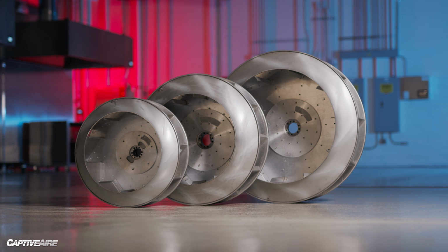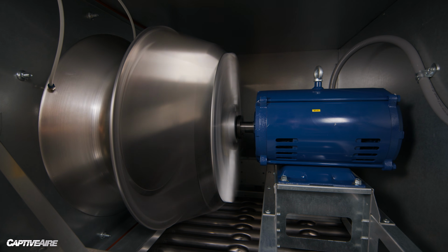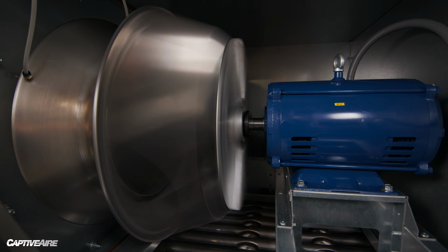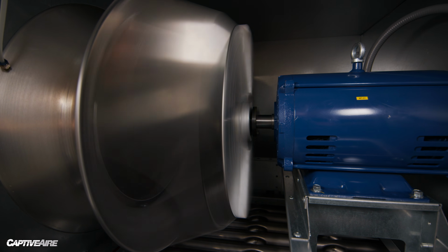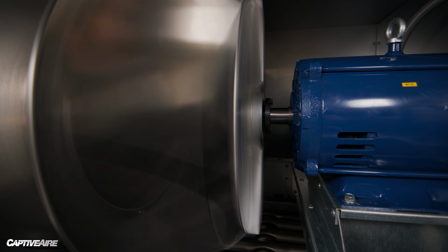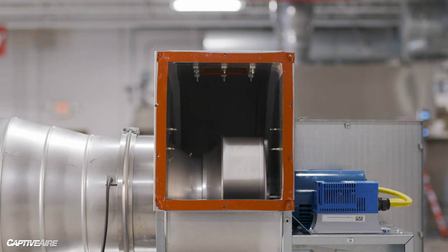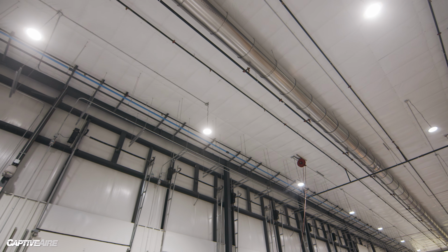In general, you kind of want to select the largest fan wheel that you can, given the motor combinations, and there's a lot of other things that go into it, like the weight of the fan, the space of the fan that you can use, the CFM and things like that. But running a larger fan wheel at a slower speed is usually much better and more efficient than running a smaller fan wheel, the same CFM, same static pressure at a much higher speed. Running that larger fan wheel at that slower speed also generally has less static pressure involved because there's bigger ducts, less noise, things like that.